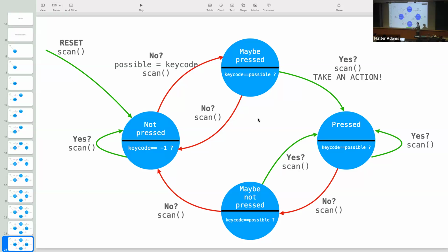And then as a subsequent step, you can change the beep to, say, a swoop or a chirp or something like that. And then you can augment the interrupt service routine a little bit so that this button means swoop, this button means chirp, and so on. So I'd recommend bringing them together, first of all, totally independently, and then tie beep production to a button press, any old button, or all the buttons, any of the buttons, whatever, and then change the sound from the beep to a swoop or a chirp.